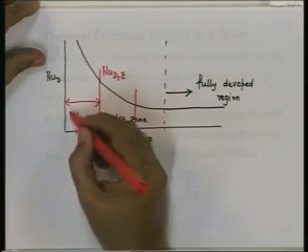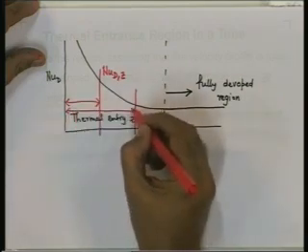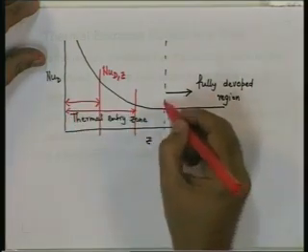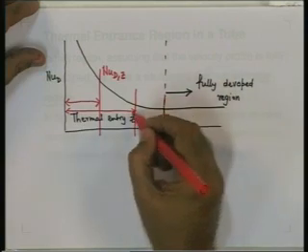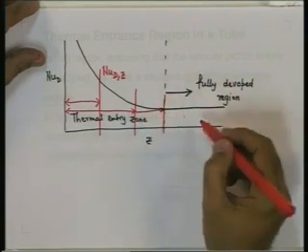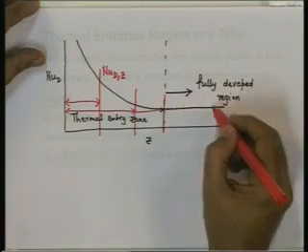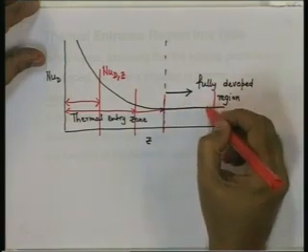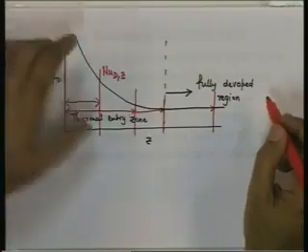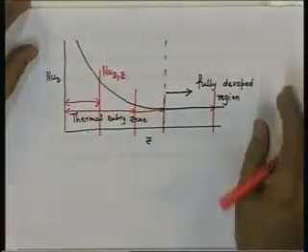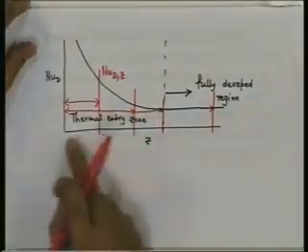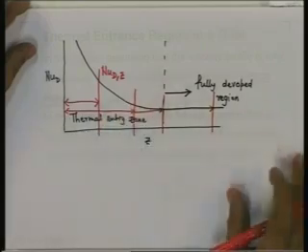Then over this length, what is the average Nusselt number? The average Nusselt number will go on changing till the end of the thermal entry zone. It will go on changing for some time in this region, but beyond that the effect of the thermal entry length will be too small for us to worry about this zone of higher Nusselt numbers.